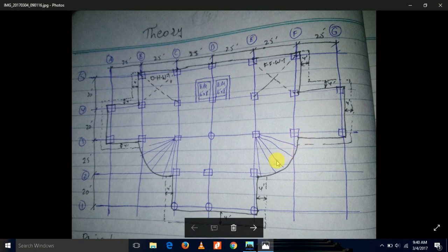Here you can see the degree as 90. If we provide a grid line at 15 degree, then it will become 7 lines, 1 2 3 4 5 6 and 7, and the distance along the radius of every grid is 25 feet, and only two grids will be defined for each radius, one here and one here, similar for each.